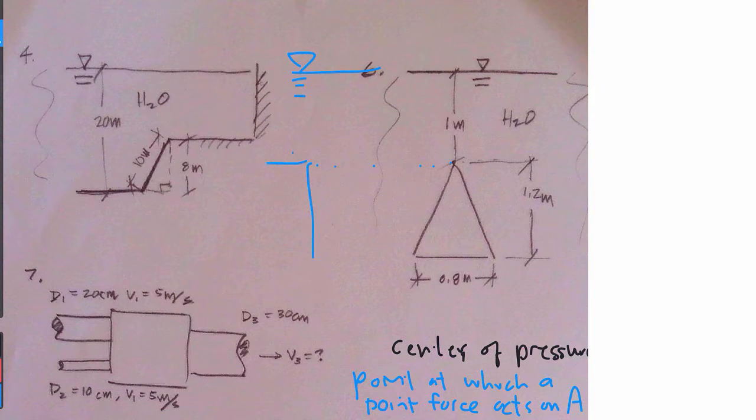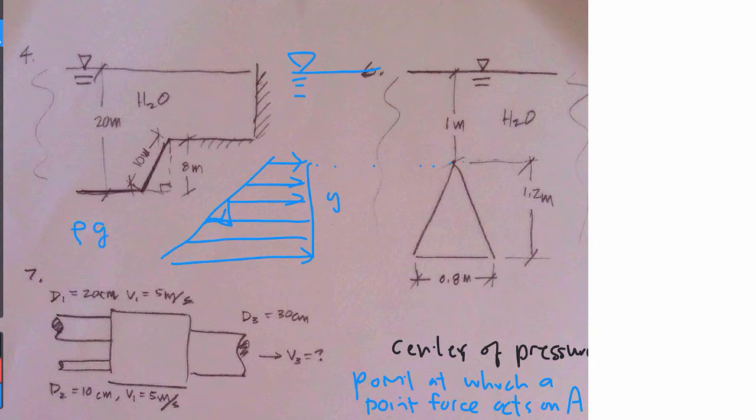So we know that underwater here, the pressure at this point, let's say if we're plotting it, is some value, but as we go down into the water, that pressure increases with depth. And we know the slope of this line, if this is y, is equal to rho times g, because the pressure as a function of y equals rho times g times y, and y is measured from this point here. So the change in pressure with y is this rho times g, that's the slope here.